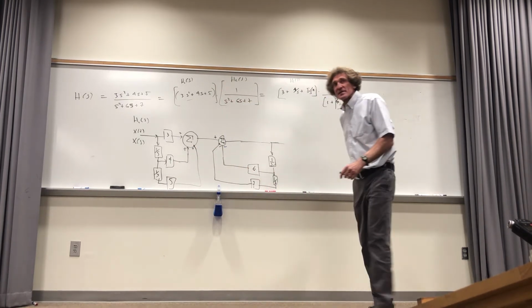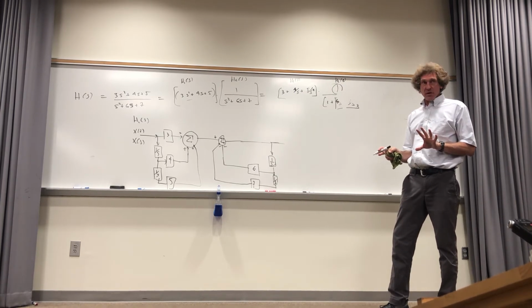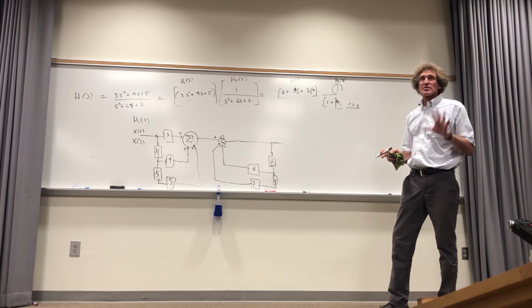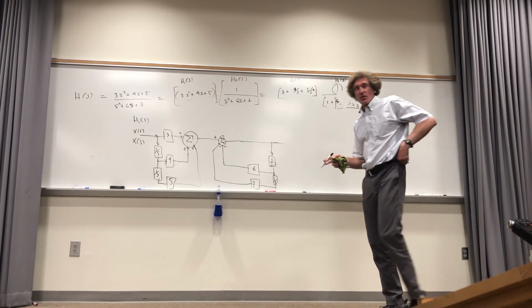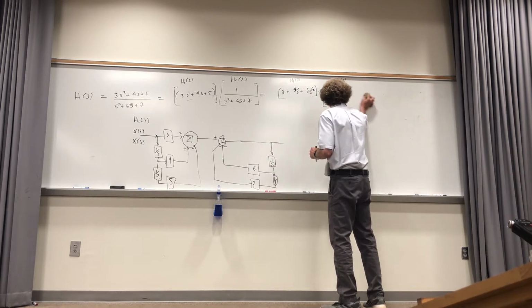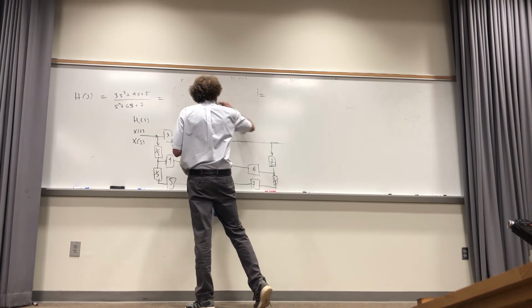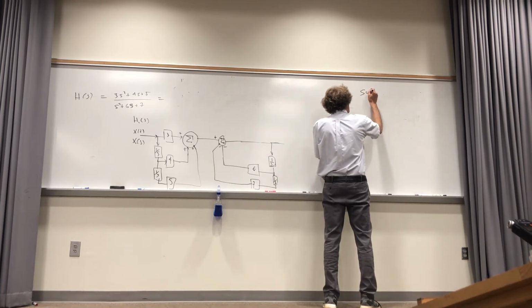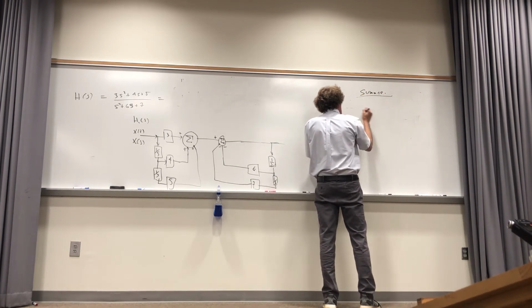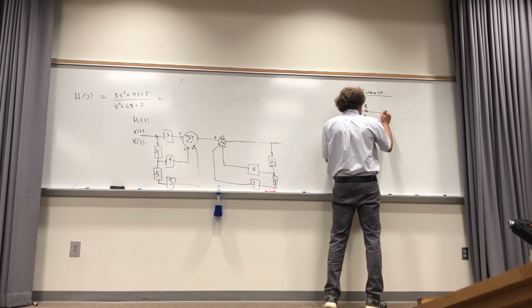All right, now about the summers, just to make sure. And I'm going to say one thing. You can probably look and find a whole bunch of designs on summers in general. The one I'm showing you is the most basic and most common one. That's the reason I'm going with it. So for a summer circuit, the simple operational and ideal op-amp summer circuit is this one. This is a summer. Simply, you're going to have 3 resistive values. Here, I'm just going to call them all R. There's no difference. Tie those together.